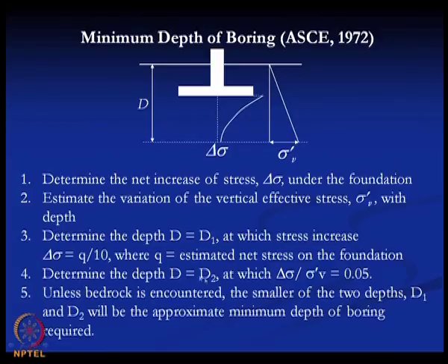Then we determine the depth D equal to D2 at which the ratio of the net increment of stress divided by the effective vertical stress is equal to 0.05. So, we will determine that depth also, where we get this condition.